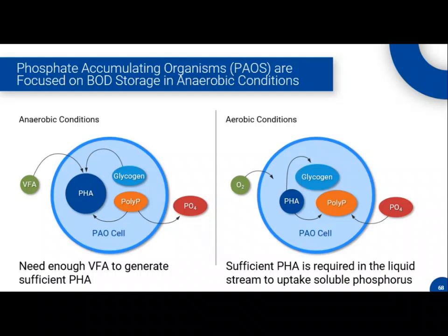We talk about heterotrophs and then these PAOs are like 15% slower. Those nitrifiers are like 30% as fast, so it's like 70% slower. So they really need to be coddled, and they become very sensitive. So when they get any kind of inhibitory impact, they're not as robust as a heterotroph or as a PAO. And so that's why we watch glycol, because it'll impact all those nitrification processes we were talking about yesterday.